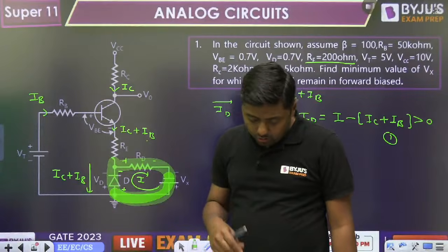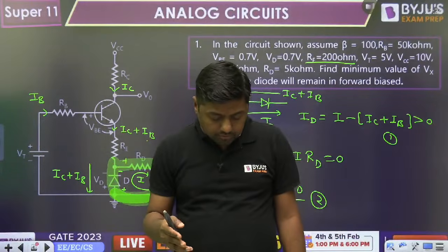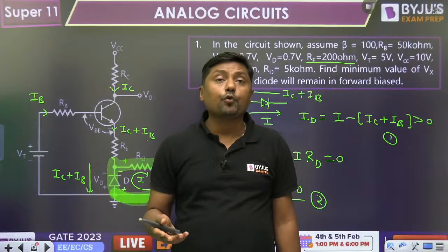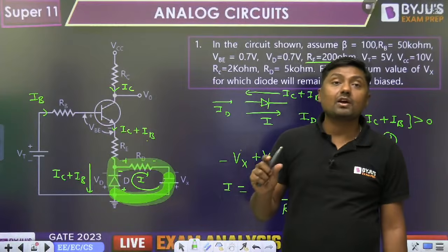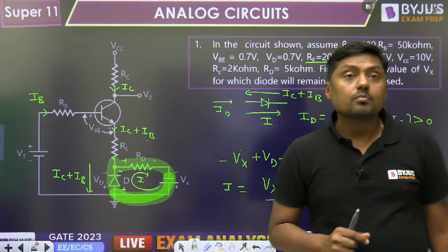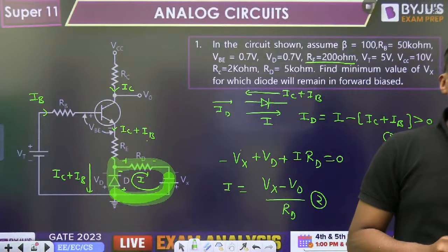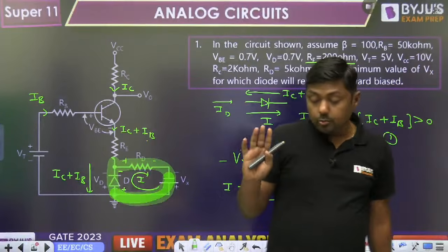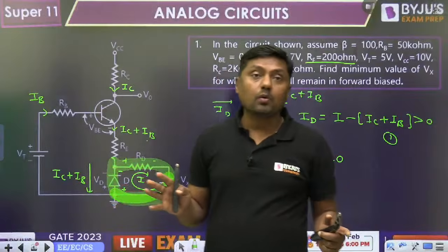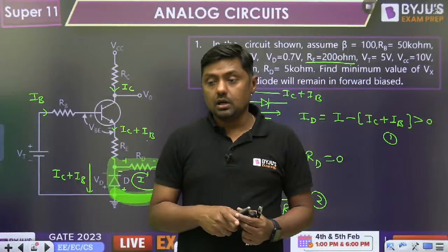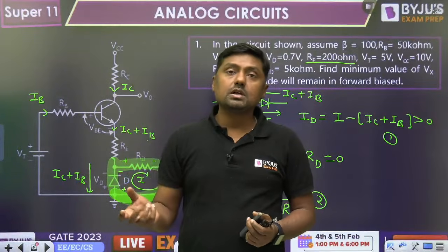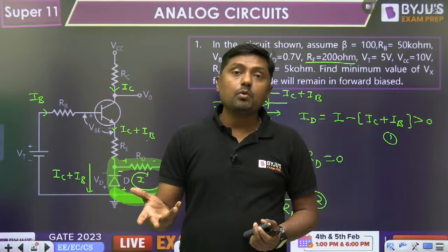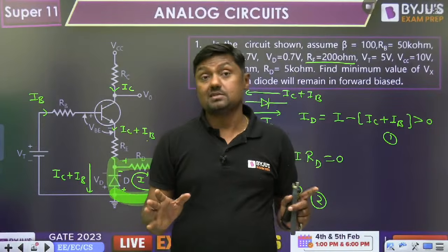You will get a value greater than 0.7 volt, around 3.49 volt. 3.49, that is the value of VCE. Maximum every question related to BJT will be in active or saturation. No, Raghuram, no. Don't be biased. Don't anticipate this type of thing. Otherwise, you will think about the active region, or in exam, it may be in saturation region. Don't be biased.